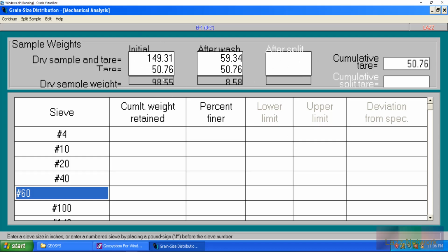because I have the total sample weight, because technically for a hydrometer it's a subsample of your main sample, where a hydrometer test you only need 100 grams. It really depends on the material type. I know, going down a rabbit hole here. Bear with me on this. So it really depends on the material type itself, where technically if it's silts or clays you only need 50-ish grams to run your test.